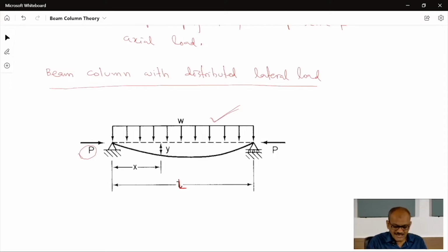So, what exactly is the Rayleigh-Ritz method? Here we assume a suitable shape function for the deformation of the system, and next we find the total potential energy of the system using this assumed shape function. Then we minimize the total potential energy, which leads to the equilibrium configuration.